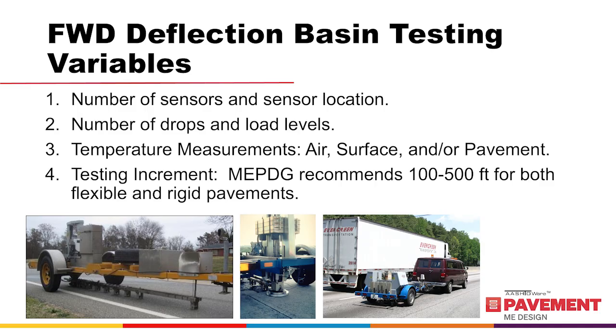Next, temperature measurements during FWD testing. Temperatures are important because they do impact the deflections, especially for thicker asphalt pavements. As the temperature increases, the asphalt modulus decreases, so the deflection basin increases. For rigid pavement, temperatures can also have a large impact on the deflection basin because of the curling and warping